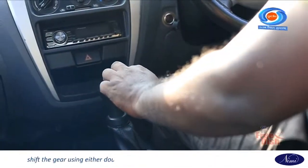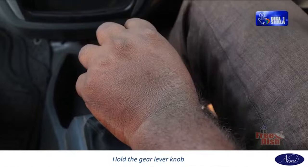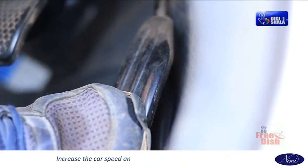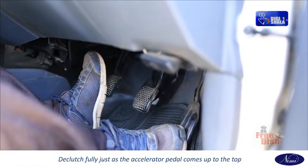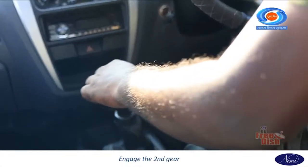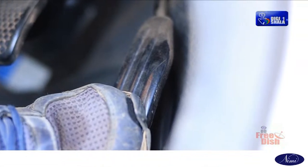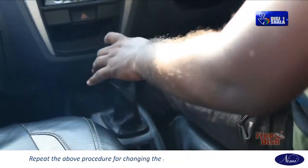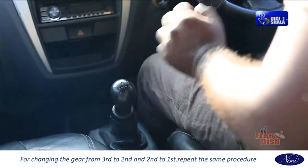Shift the gear using either double declutching or single declutching smoothly. Hold the gear lever knob. Increase the car speed and then release the accelerator pedal. Declutch fully just as the accelerator pedal comes up to the top. Shift the first gear to neutral. Engage the second gear. Increase the car speed by pressing the accelerator pedal. Repeat the above procedure for changing the gear from second to third. For changing the gear from third to second and second to first, repeat the same procedure.